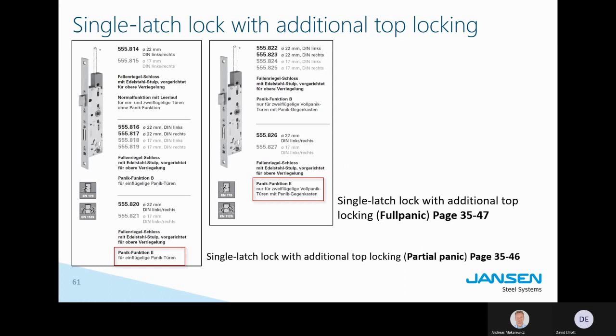One more thing I would like to mention at this stage. I don't know if you guys have the same regulations in South Africa. This is how Europe regulates it. Public buildings versus semi-public buildings, where the users know the way out, the escape route, are described by two different norms. The norm EN 179 will define all the requirements of a fire or escape door in a semi-public building. And here you see there is a handle. You can use handles on these doors.